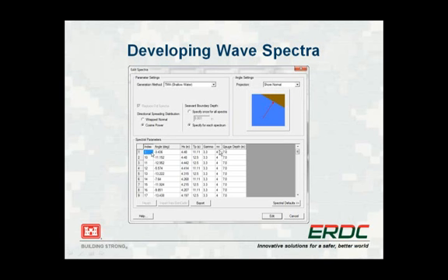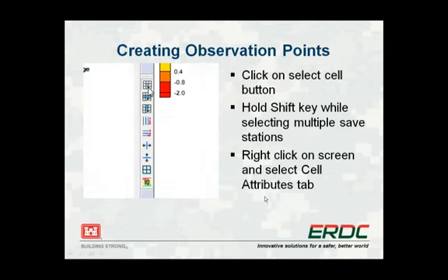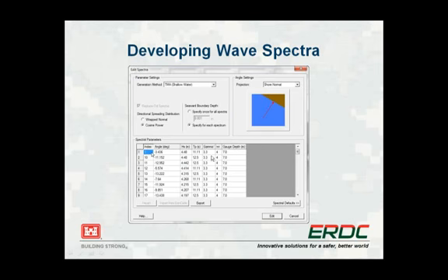Gamma and the spreading factor are the defaults, 3.3 and 4, but if you click on Spectral Defaults, you can see what they are for increased wave periods. Your gauge depth is just whatever your offshore gauge depth was. Sometimes it may be necessary to bring your gauge depth in using some kind of WIS Phase 3 transformation to allow for the depth change from your gauge to the edge of your CMS-Wave grid.